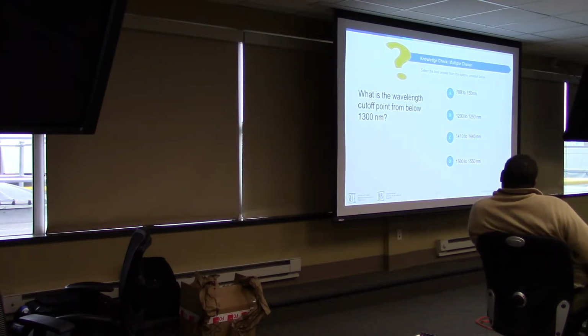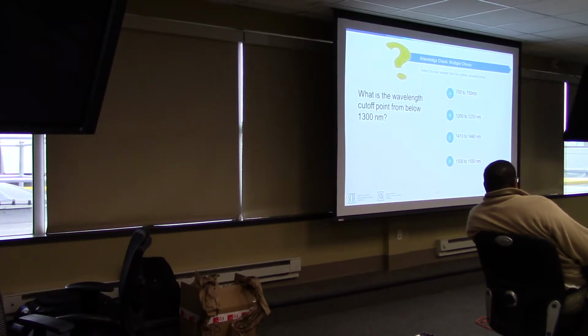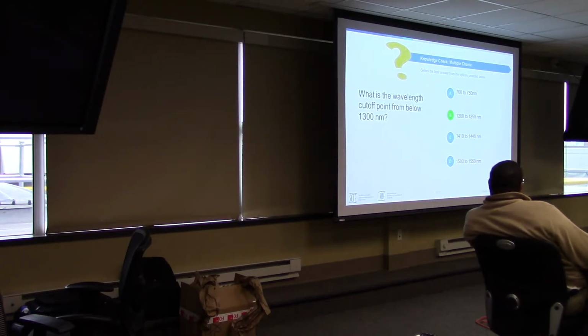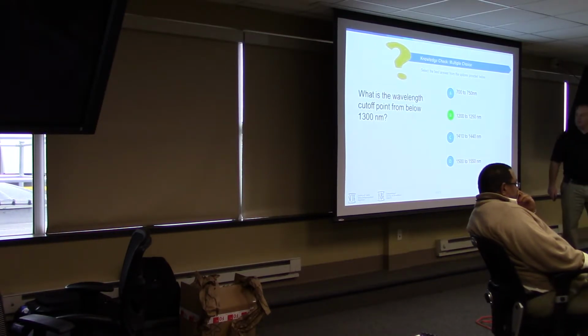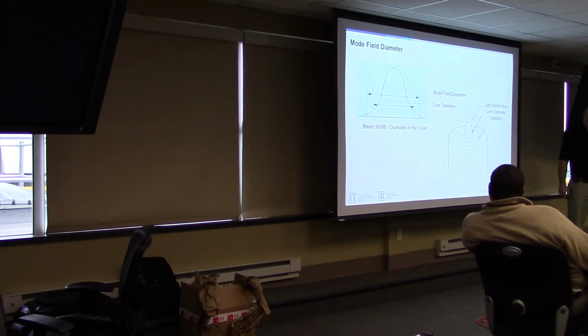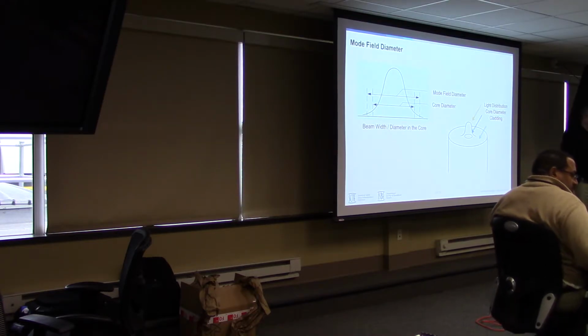It's not quite that it goes from multimode to single mode; it's really where you can only propagate one version of light. You said above 1250. Yes, that's it. Anything above 1200 to 1250, we can only propagate one mode of light. So that's where you have to multiplex. That's why multimode uses a wavelength less than that, typically 850.